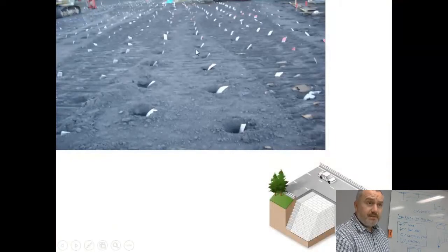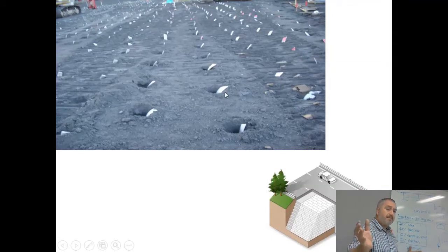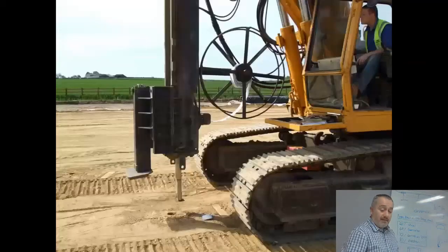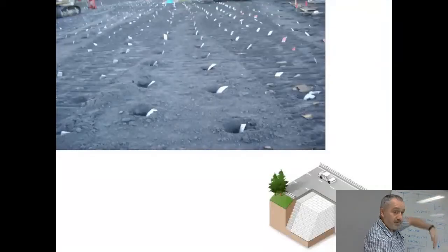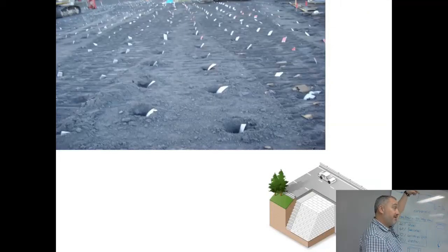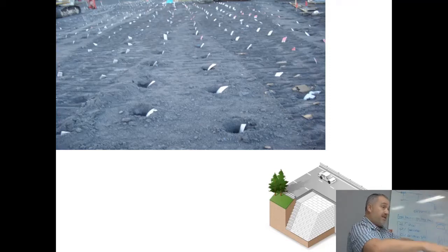Has anyone seen this tape before? Like this filter tape? When you have an embankment, it's going to settle over time, and they have this machine that punches in, a bit like goes to depth, a filter tape, and what happens is that the water that is in the embankment goes to this filter tape and then comes over to the surface, and it speeds up the amount of settlement. So that's what that is.